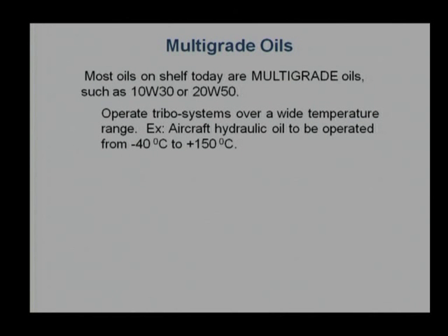An interesting thing is that when we go to a market, most of the time available oils are multi-grade oils. Let us take an example as some sort of classification: 10W30, where W stands for winter, and that divides it. The left hand side of the W refers to winter oil, the right hand side refers to the hot temperature condition. In other words, this multi-grade oil has SAE10 characteristics as well as SAE30 characteristics by and large. In the second example, it also has two characteristics, SAE20 and SAE50. That is why they are called multi-grade oil. It is not one single grade, it contains two grades.